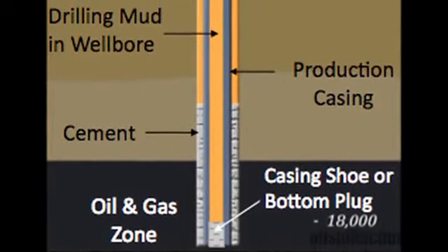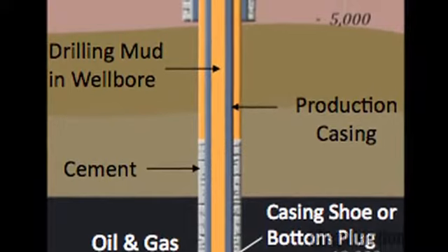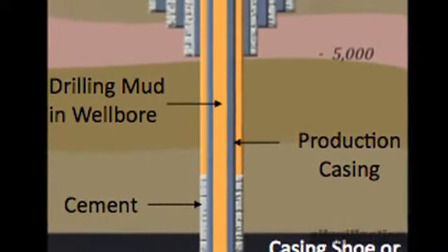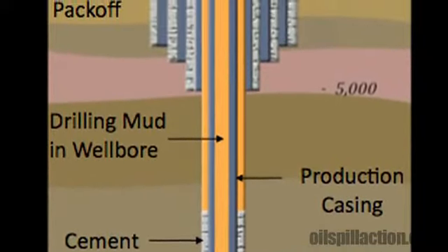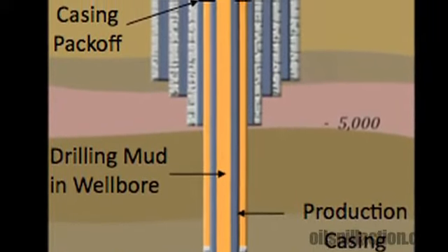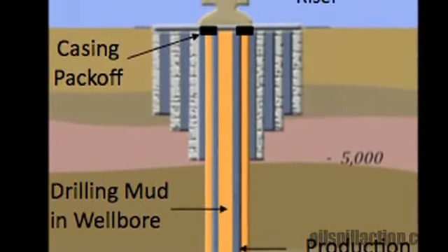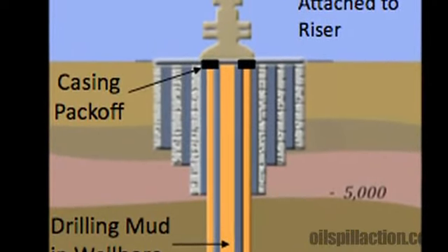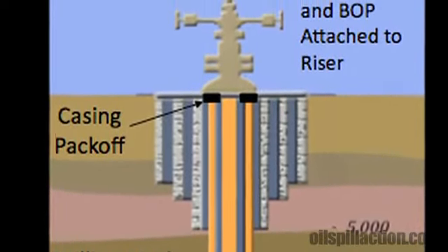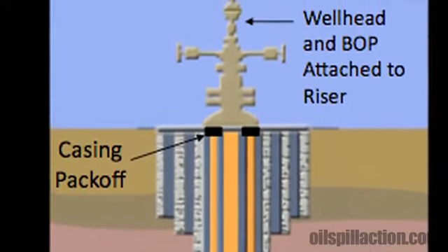Once that is accomplished, it's necessary to finish the well and move the rig off-site. After the requisite pressure tests are done confirming the integrity of the casing job, a cement balance plug should be set inside the casing to prevent against a blowout. Once the balance plug is set and pressure tested, then the mud in the riser, the primary means of well control that's in the pipe from the rig down to the blowout preventer, is removed, and seawater is placed in there, and then they can remove the riser and the rig can move off-site.